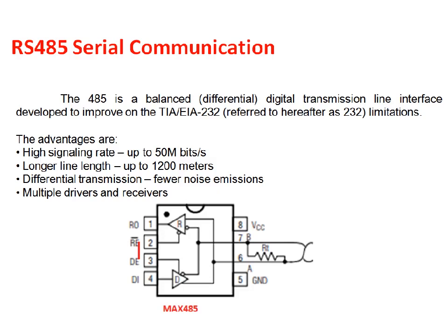In this video, I will discuss RS485 serial communication. RS485 is a balanced differential digital transmission line interface developed to improve the limitations of RS232. The advantage of RS485 is a large data transfer rate and longer distance between the sender and receiver.